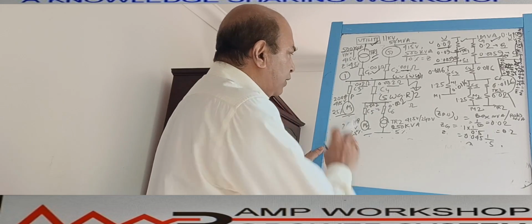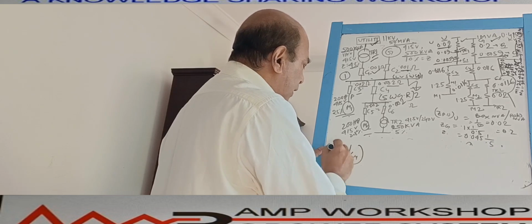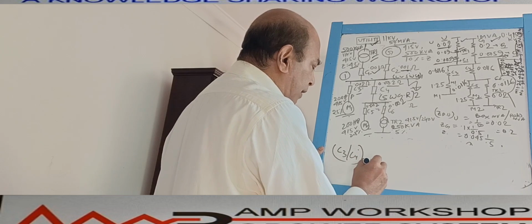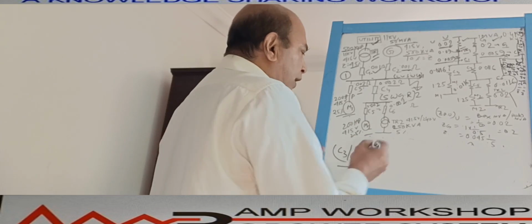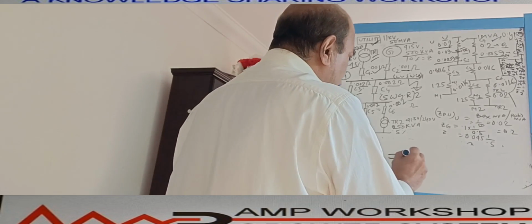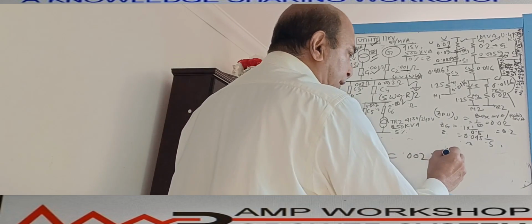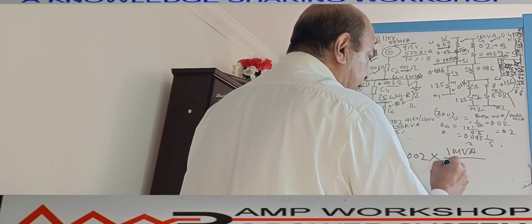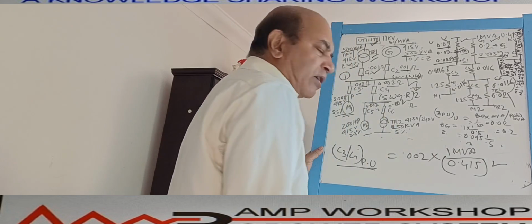How do we calculate this per unit value? C3 or C4, both have the same per unit value based on base MVA. We calculate based on the base MVA, 1 MVA. That equals how much? Ohmic value 0.002 into, what is the formula? Base MVA 1 MVA by kV squared, that is 0.415. That is the ohmic value to per unit value conversion formula.